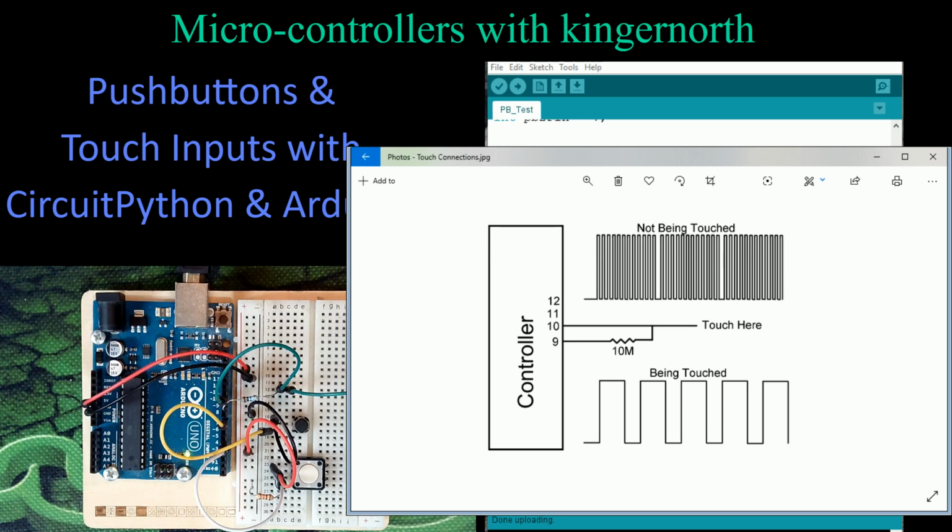to complete the circuit. If that ground plane is missing, it may not work very well at all. You may not drain enough out of it through the static in the air in your hand, and your body's transmitting that out through the air to ground the circuit. So it may not work very well. It works really well in a car because the whole body of the car is a ground plane. It works really well in an apartment building or a building that uses capacitive touch for the buttons because you have a large infrastructure of ground around you.